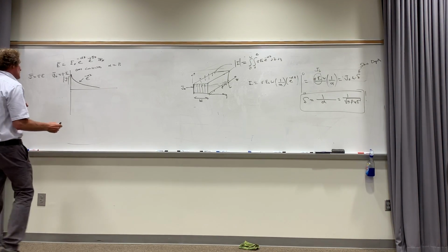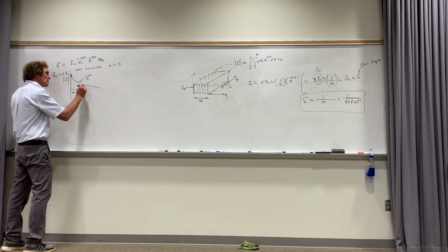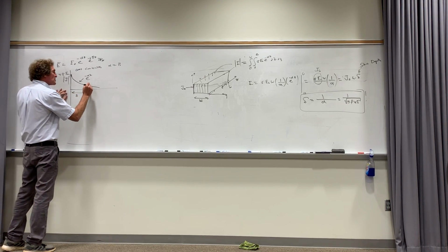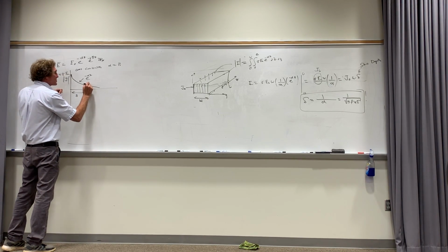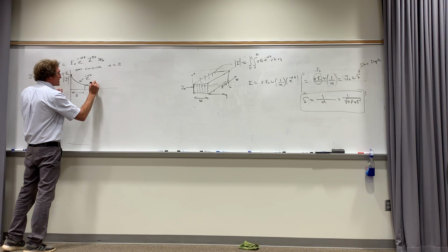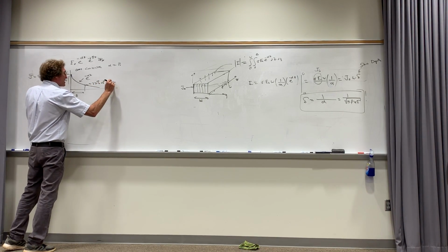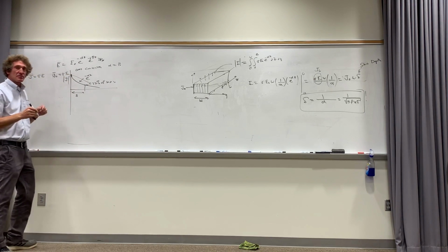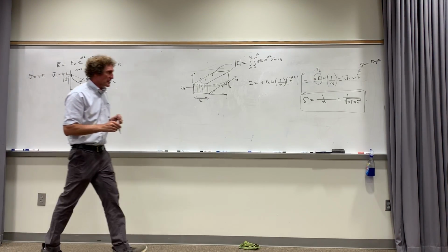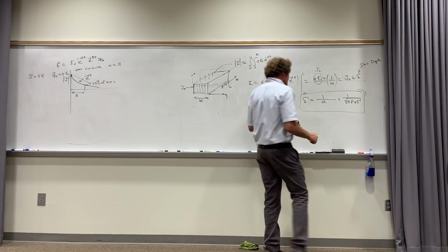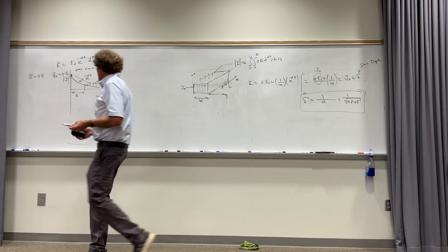And really, what I'm going to say is this. When I'm 1 skin depth down, and you can show this, the value here is going to be 63% less than that. So this value is going to be 37% of maximum, and that maximum would be here. Do you all see what's going on here? Keep that in mind. Now, here's where skin depth is really applicable. It's in problems where you talk about resistance of certain things, like wires.